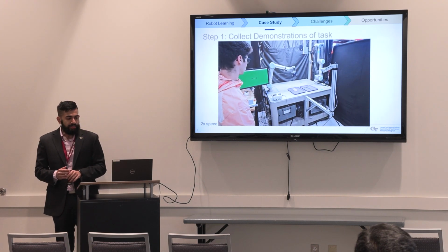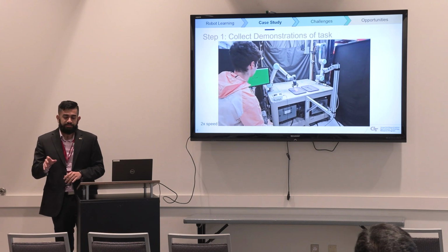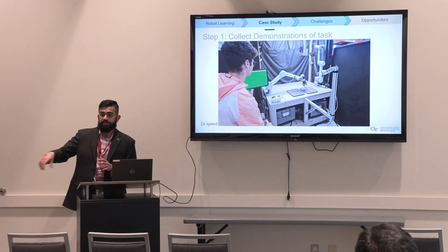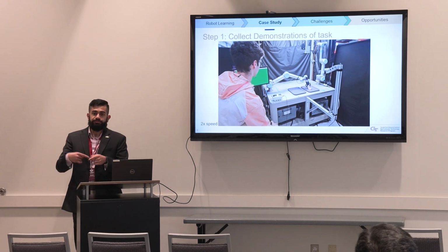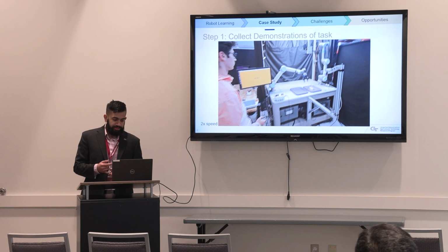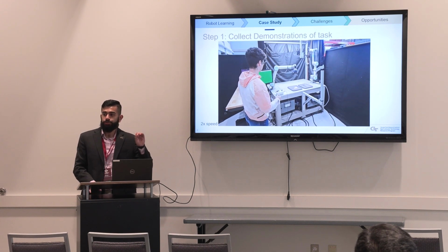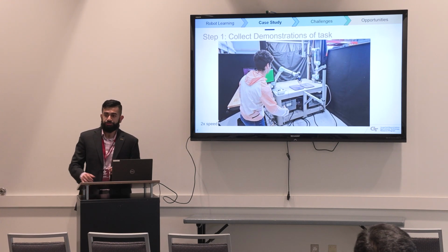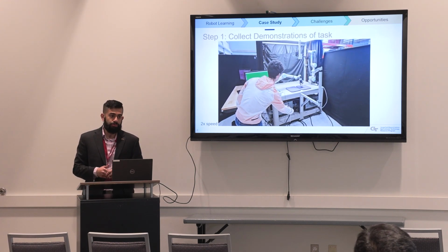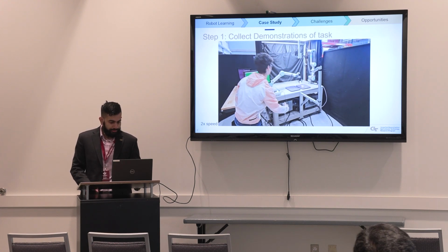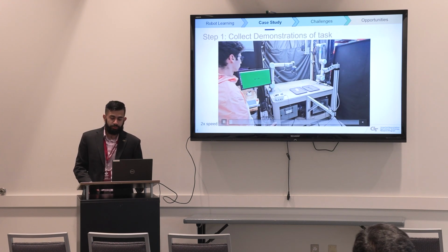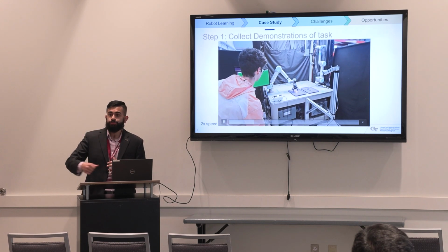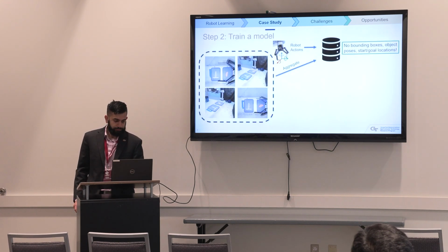So the first step here is to collect demonstrations of that task. Here we have a simulated setup where we're picking up that chicken breast and aligning it on the tray on the right to simulate how it would feed into that water jet. As you can see here, this is quite easy to do for even someone without any robotics experience or any programming experience, right? They're just using a VR joystick to teleoperate that robot. At the same time, we have all these cameras around the work cell which are saving all that camera data, and trying to match it up to what the teleoperator is doing.